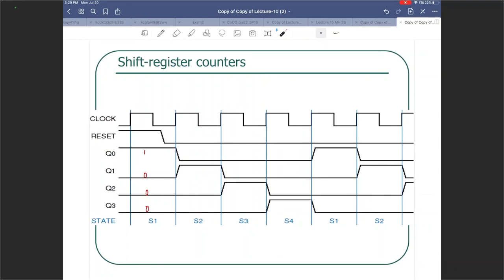After the next positive edge, after we loaded, we made it into a shift left, right? So at this point, we transitioned from a parallel load mode into a left shift register mode by adjusting S0. And as you are clocking things through, what happens? That one is now coming down.